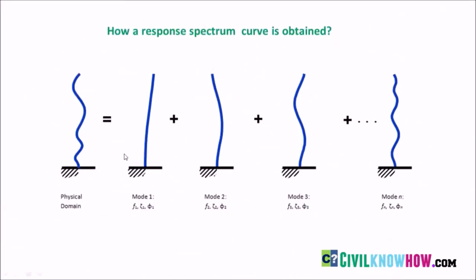Let's assume our structure to be a single straight line. When the seismic acceleration is applied on each joint of the model with respect to a single degree of freedom, different mode cases with unique modal response are obtained, that is, from mode 1 to n number of modes. In the response spectrum analysis, we combine all these modal cases to obtain a single response for the structure.